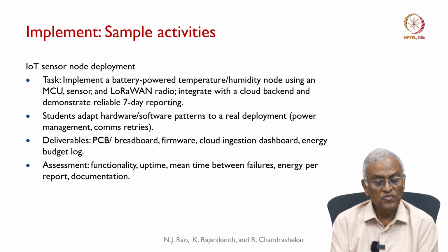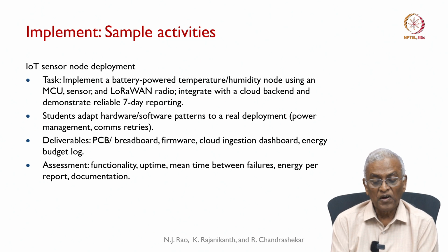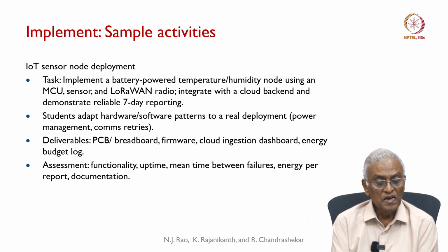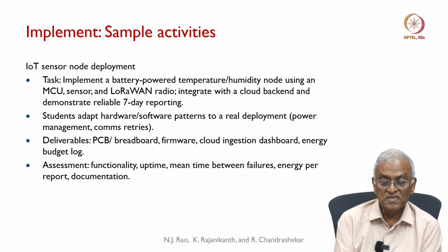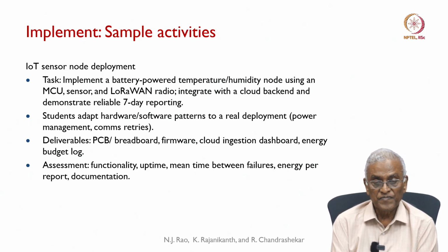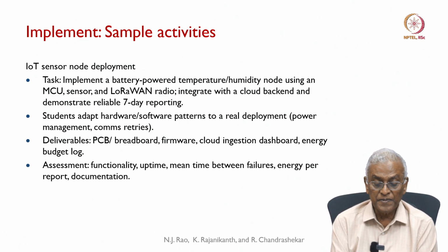Students adapt hardware and software patterns to a real deployment, that is power management, comms, retries and so on. Deliverable: a PCB or a breadboard, firmware, cloud ingestion dashboard, energy budget log. These are the outputs they have to produce, and then assessment is functionality, uptime, mean time between failures, energy per report, documentation.